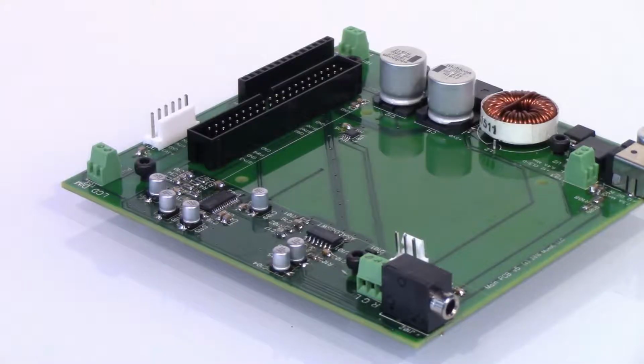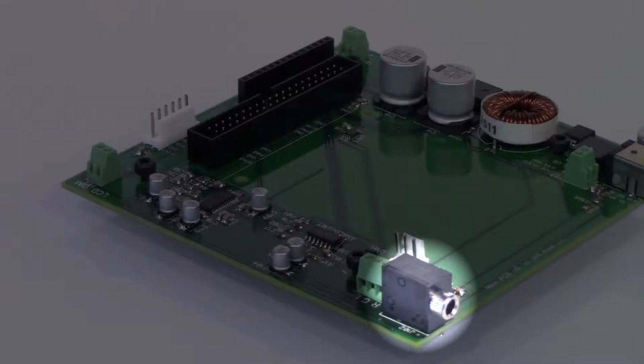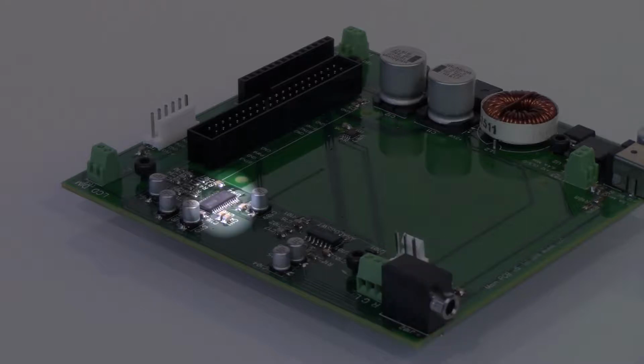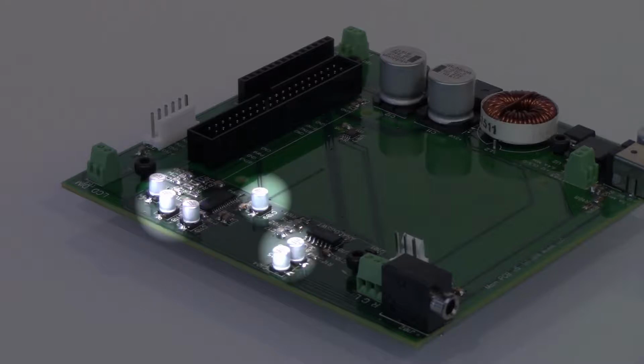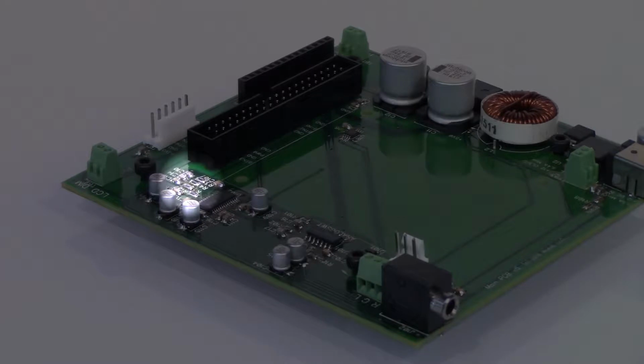The audio section features an external 3.5mm stereo input port, a 24-bit TI Burr-Brown DAC, Panasonic bipolar electrolytic caps, Samsung 5% ceramic caps, Vishay 1% resistors, and a quadruple bilateral analog switch for selecting which line level stereo signal is sent to the amp board.